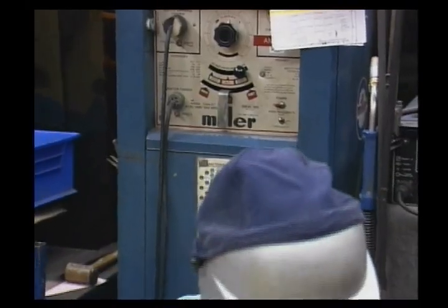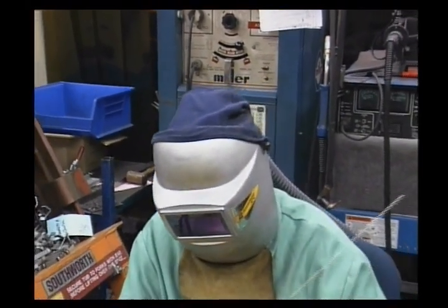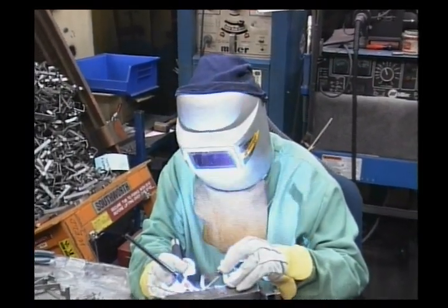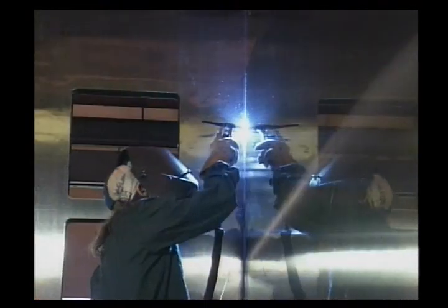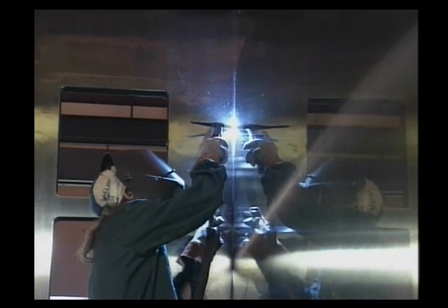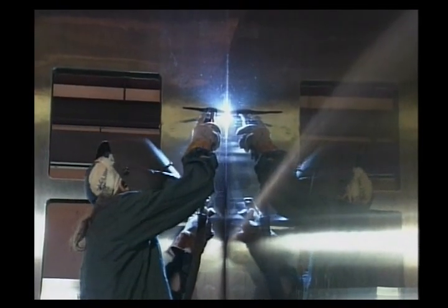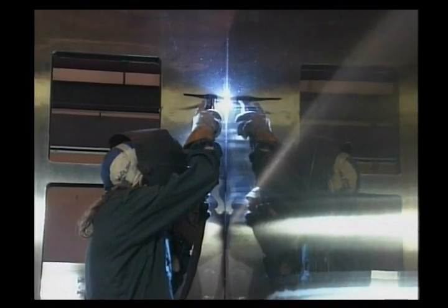The gas tungsten arc welding process employs either an alternating current or direct current power source, depending on the type of metal to be joined and its thickness. Some power sources provide pulsating direct current with variable frequency. These adjustments allow better control of the molten weld metal when welding thin sections and when welding in other than the flat position.